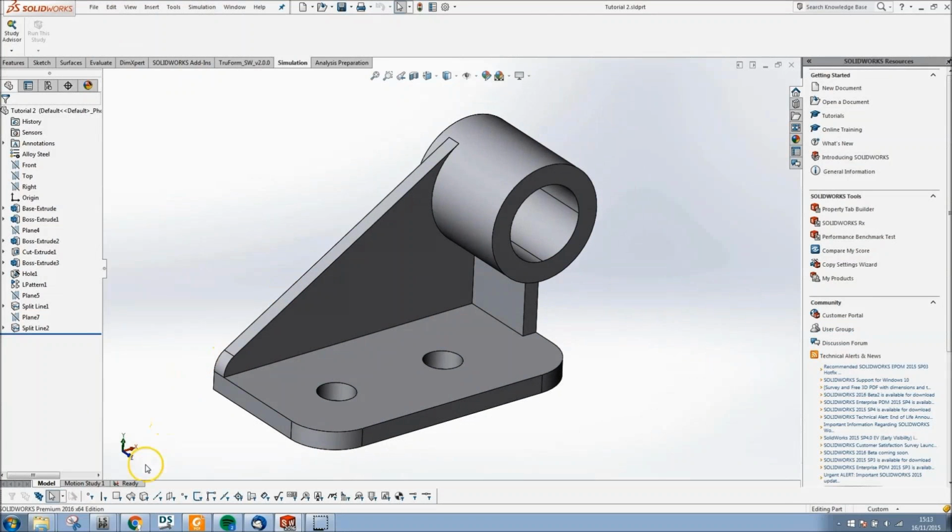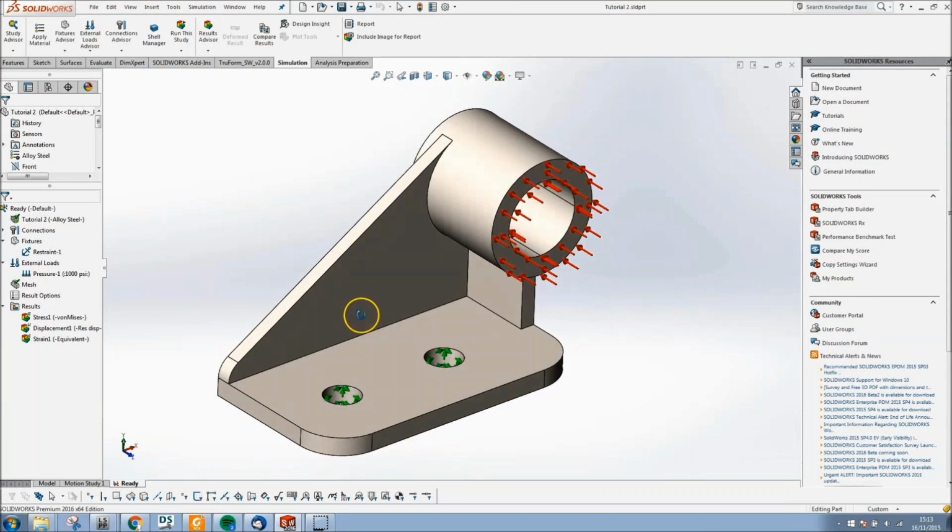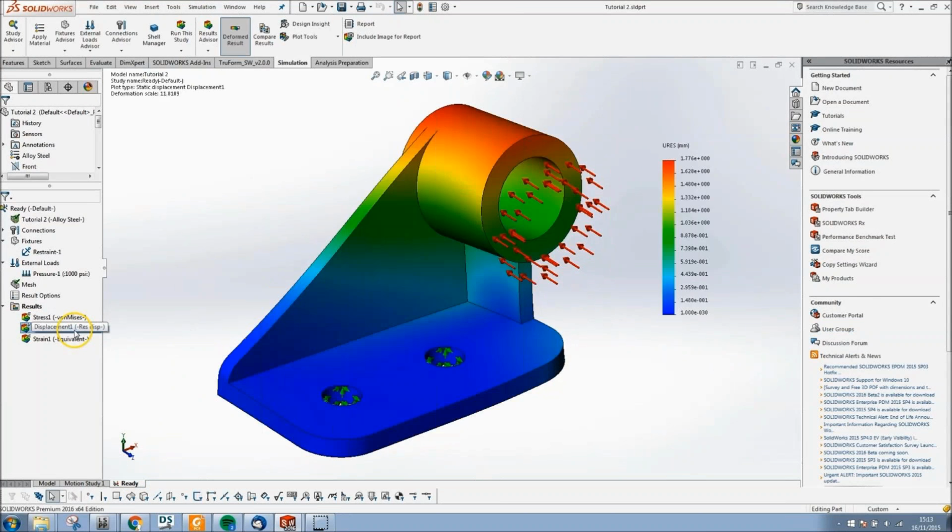So here we have, again, I think this is actually one of the first tutorials in the SolidWorks simulation module. So what we're going to do here is just take you through the performance. As you run the model to start with, we have a baseline displacement of 1.7 millimeters. And for our case, we're going to consider that this is too much. We want to reduce that displacement.